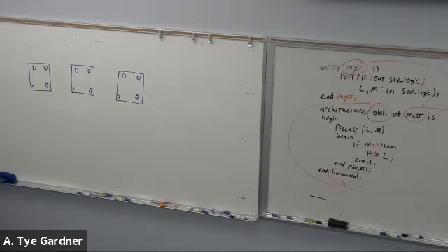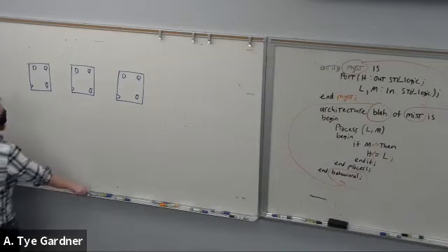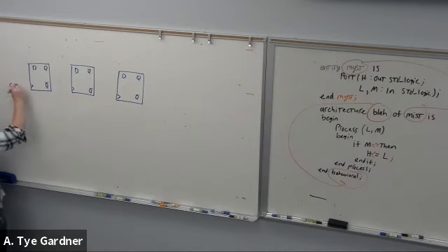Okay, next question. Trying to plug along right here. This question is going to read: using these D flip-flops, design me an asynchronous clock divider to get a clock 8 times slower than the input clock. This is my clock in. Make me an 8 times slower clock using only the flip-flops.